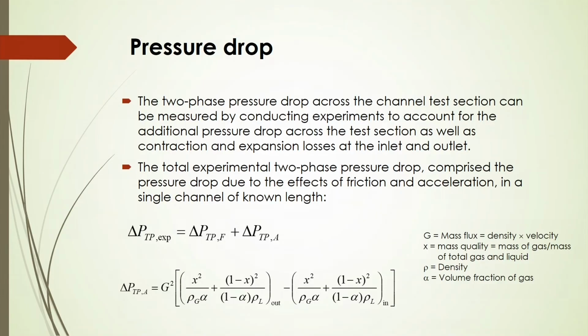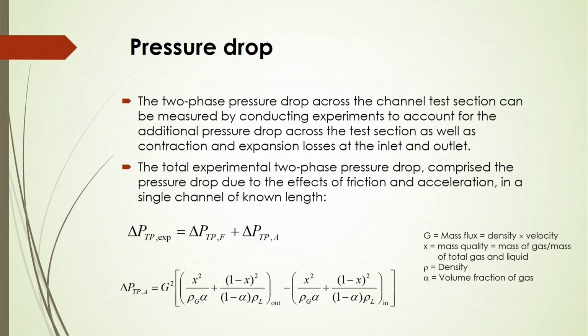And also pressure drop is one of the important aspects of the design of a microchannel based reactor, because based on this pressure drop there will be energy dissipation, and based on that energy dissipation is how the mixing happens inside the microchannel. This is one of the important aspects. So, that is why you have to know the frictional pressure drop inside the microchannel, and how to analyze and predict that frictional pressure drop.